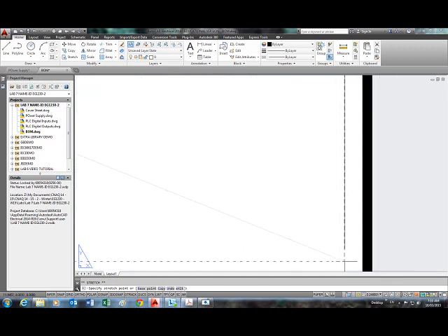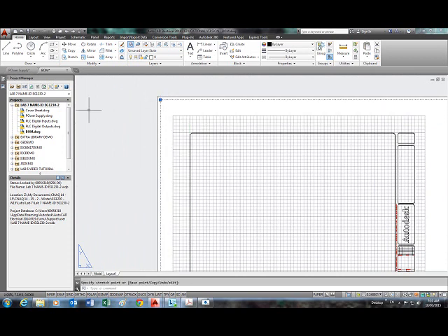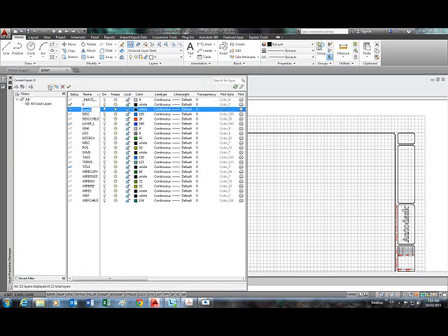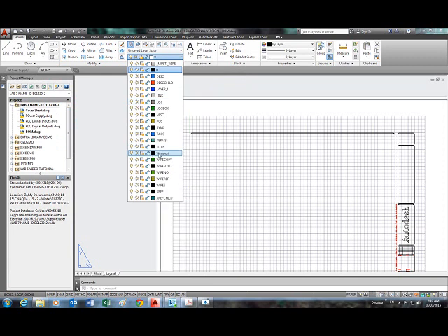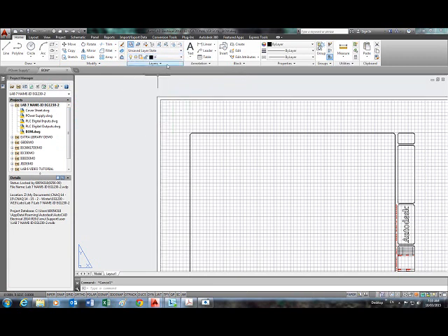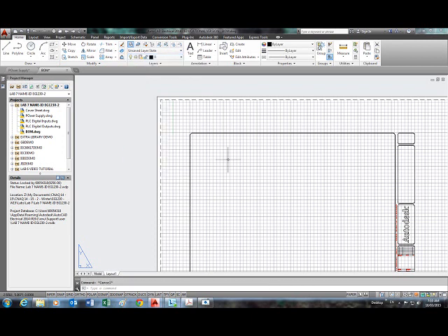adjust, and then escape, create a new layer, choose the viewport, move it to the new layer, escape to go to current, turn off the layer viewport so it doesn't print, double click and zoom extend.